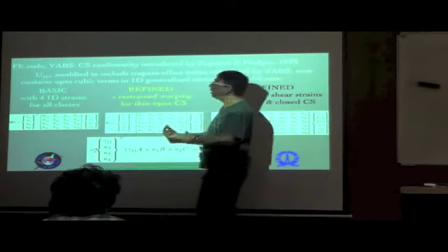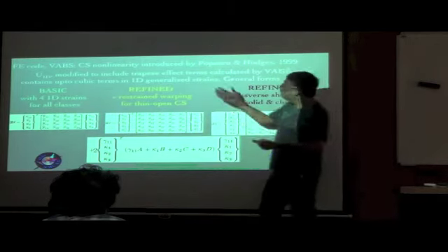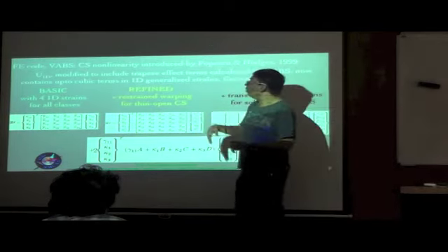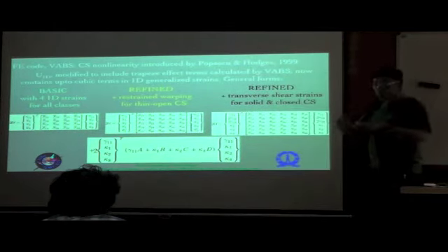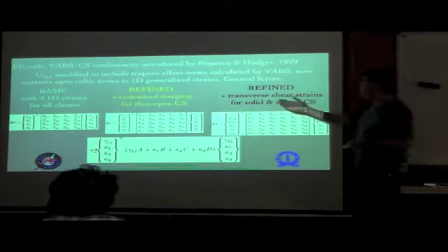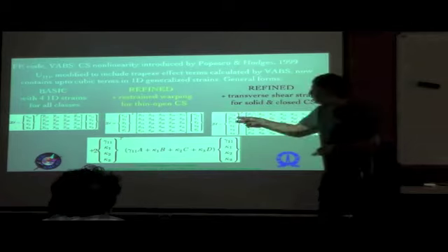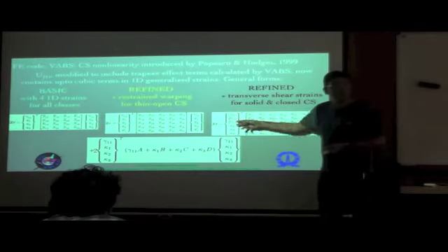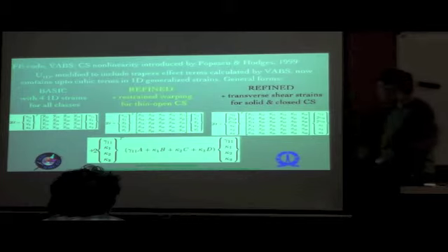That's after which you start refining it, and two sets of refinements that we have already looked at. One is where you have thin-walled open cross-section, and therefore you basically have restrained warping coming in, that is kappa 1 prime is coming in. And the other situation where you have short stubby beams, basically solid cross-sections and or closed cross-sections. Then in such situations you want to explicitly bring out gamma 1 to gamma 1,3 because you're focused on certain kinds of behaviors. For example, in terms of high frequency dynamic behavior, in such situations you basically look for this 6x6.